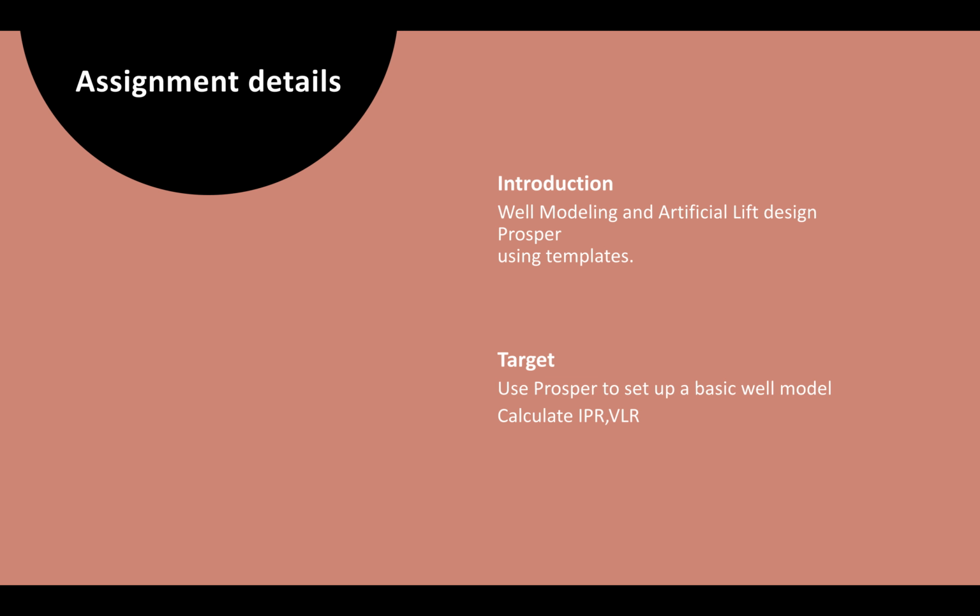In this assignment, I will use Prosper to set up a basic well model, which requires fluid characterization, IPR and skin modeling, VLP construction, and matching them. And finally, artificial lift design and optimization.